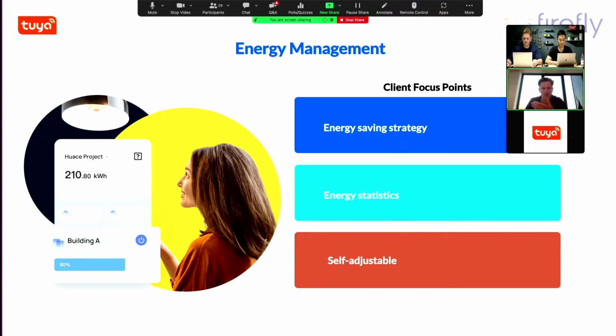And the other one that is even nicer is that you can combine the sensors together with the light output from the windows. So if there's light from the outside inside the room, they can dim the lights to save even more energy. And by making all these different strategies work together, you can save up to 60% extra on top of your LED savings. That's a fair amount.